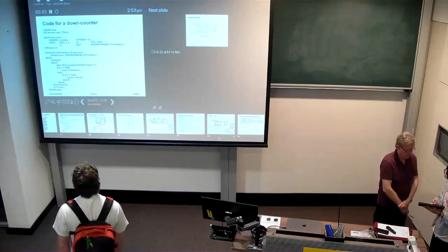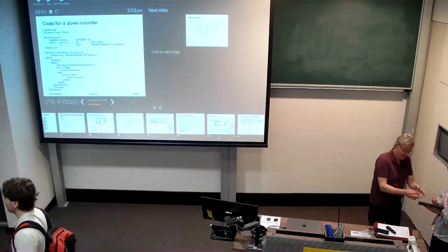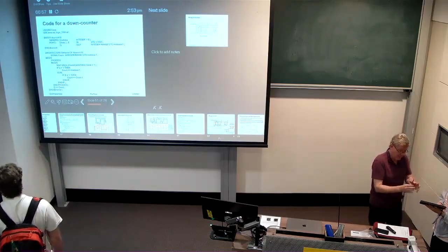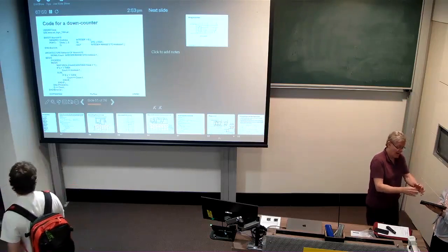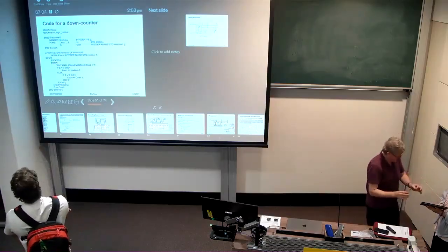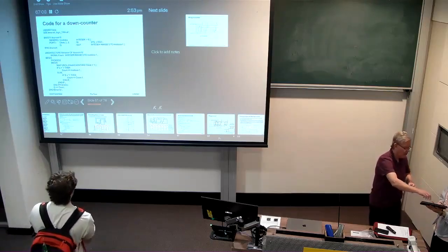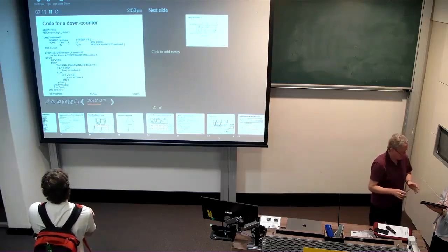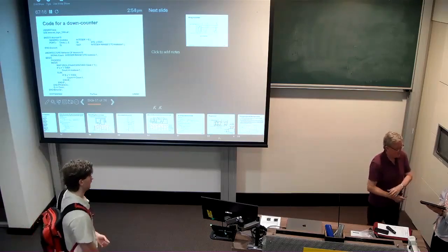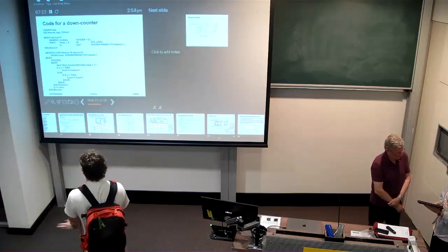How big is it? I'm not saying that it's equal to delta. I'm just giving you an argument as to why there is a period of time that you have to wait after the clock goes high before you're allowed to change D safely. If you change it before that period of time, which looks like delta from this analysis, it can impact the output of the flip-flop. So why is it not equal to delta?